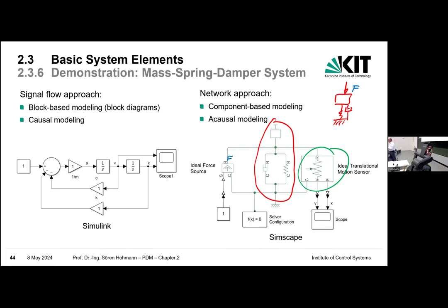In addition to that, you get the question of recuperation of energy. What we know very well, but at that time I was responsible for the braking department, therefore I was quite heavily influenced by that. At that time, we had just no brake-by-wire system. Why do we need a brake-by-wire system? In classical cars, you press the pedal, then you have a hydraulic loop, and you end up at the brake discs. No recuperation anywhere. If you want to recuperate something, then the electrical machine brakes for you.